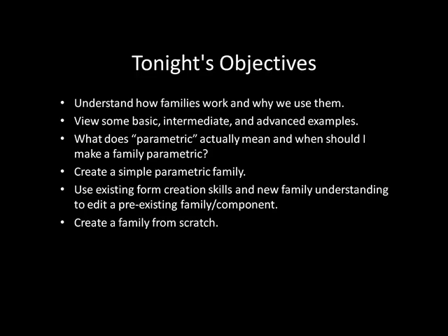But basically a family's everything without it being everything. The easiest way to explain it is like furniture systems, toilets, commodes, baths, showers, anything like that. Anything that takes up space that's not really a wall is a family. Walls are technically families too, but they're just not the type of families you can create. They're system families, which are the ones that come with Revit that you can't really change or edit except through their own properties dialog box, and those include walls, floors, roofs, things like that.